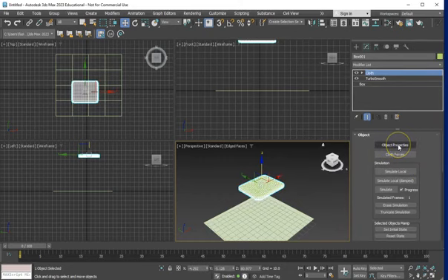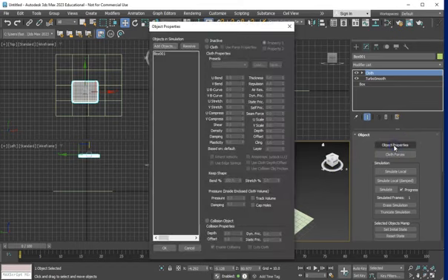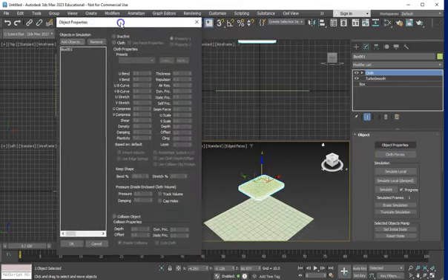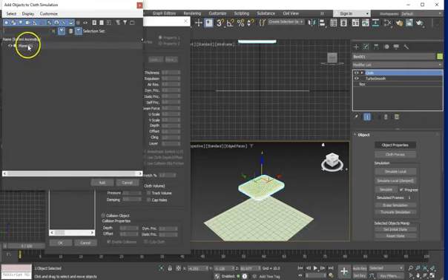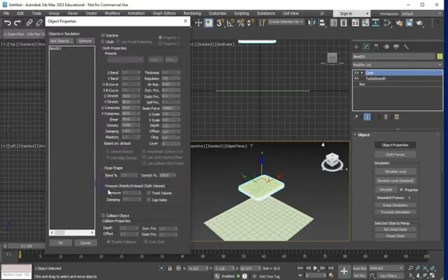And we need to also give some details about the objects. This is box 1, and we have the plane for our floor. So we need to choose both of them. The plane will be our collision object, so it will act like the floor of this world.